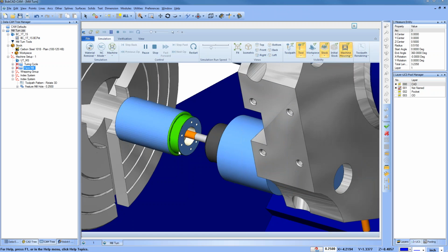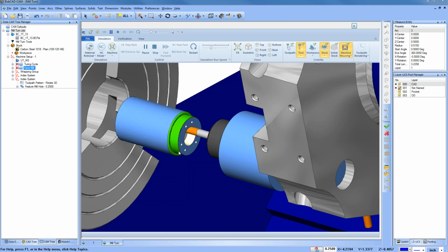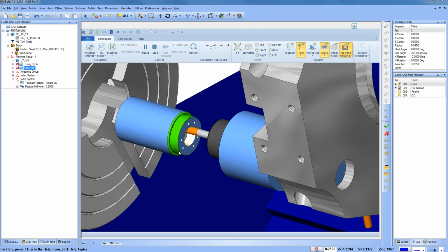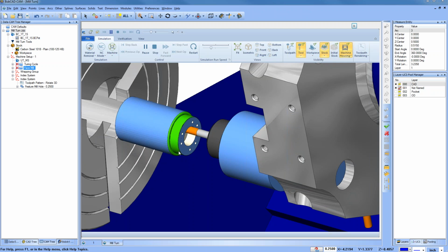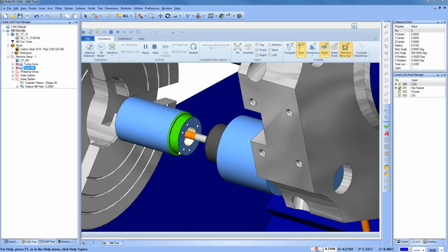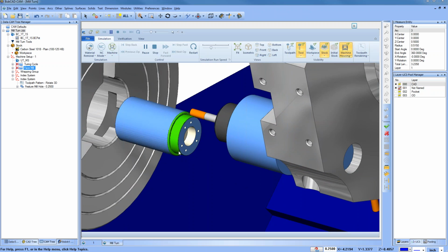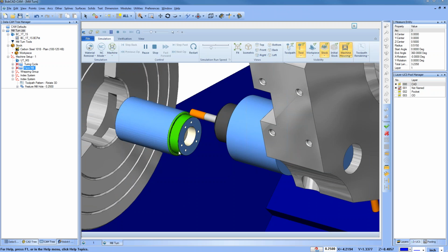Yeah, Randy, if you look, when I went to simulate it at first, I had reordered the machining order because of how I dropped the features into the group. Now that I went through and adjusted the machining order, I started to do it by the order of the features in the group, but then I went in and adjusted it in the machining order through the CAM tree, and you can see now it's cutting in the order that I wanted it to. So hopefully that was good.